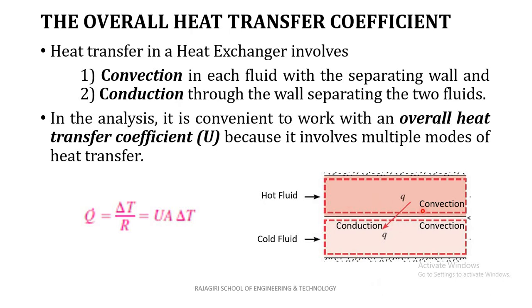Okay, so on either side of the separating wall we have convection heat transfer, and across the thickness of the wall we have conduction heat transfer. Okay, so it is convenient to work with the overall heat transfer coefficient in case of heat exchangers.